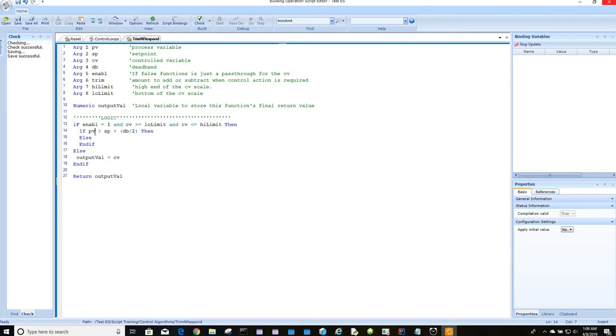And our set point is going to be, for example, 85%. We want all our dampers in the whole building to be at 85% because we've determined that's going to be the most cost-effective place when there's very little load, in order to maintain minimum